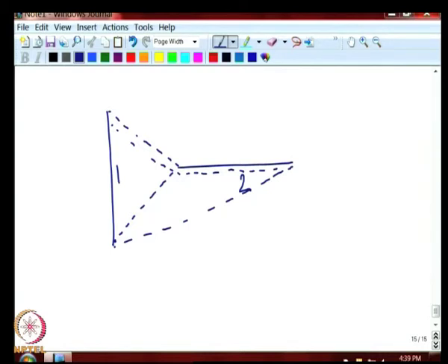So, these are the two parallel strings, and you can convince yourself that any radiation leaving 1 not reaching 2 has to go through the parallel strings. On the other hand, any radiation which leaves 1 and reaches 2 does cross the cross string at one of these points.